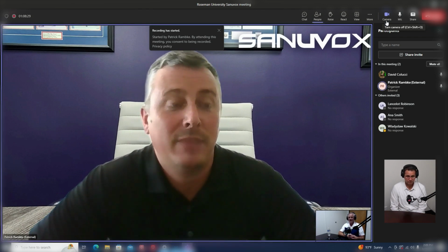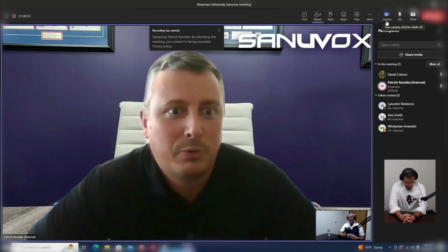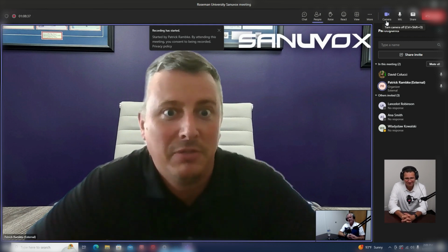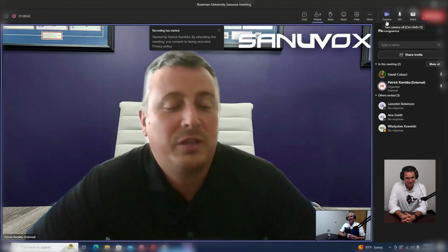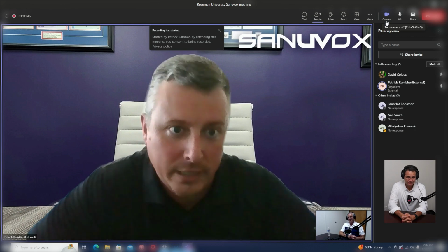And a lot of them, actually all of them, are not sized for the exact ductwork, because that would put way too much stress on a system. So they'll just do maybe a 2 foot by 2 foot square. Right. Illuminate it with UVC to activate the catalyst, and it scrubs it, but it's going to require multiple passes before it gets the job done.